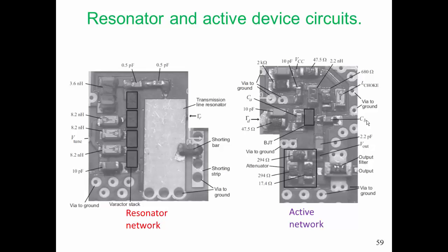And here's a little bit more detail on our resonator and active networks. The connection is from that point there where we measure gamma R and this point here where we measure gamma D. So gamma R and gamma D are reflection coefficients that we determine in simulation, but we also measure these because we find in microwave circuits, especially above a few gigahertz, that simulation on its own is not enough to get a working circuit, because in simulation we can't take all possible effects into account.